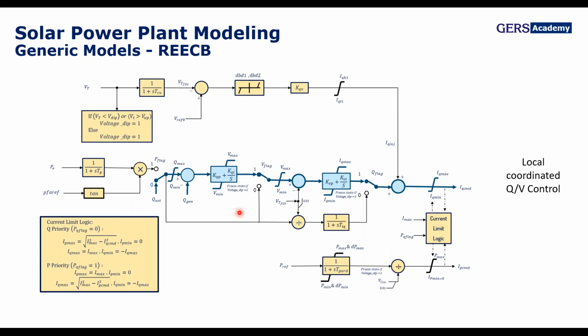The last one, probably the most common that we have seen for a couple of inverters, not all of them, is this one that uses PI controllers. I'd say it is the most robust since they use not only the reactive power signal but simultaneously the voltage signals. So controls using this loop are faster than the other ones.